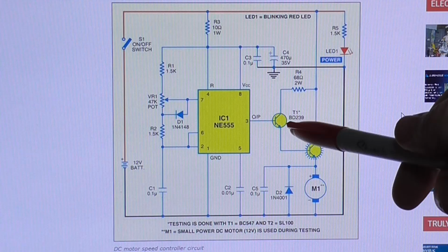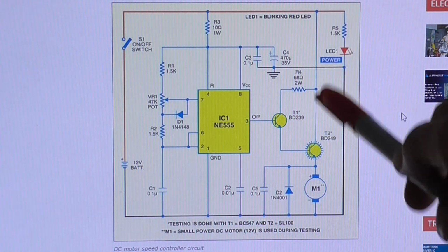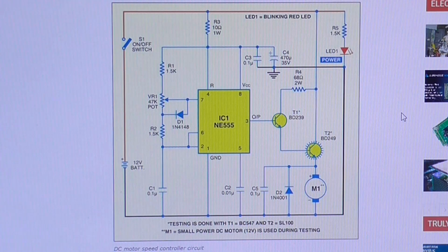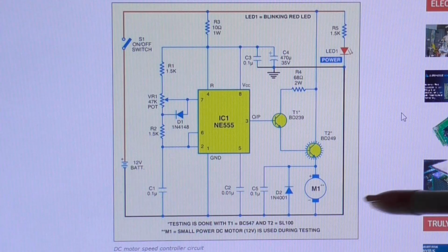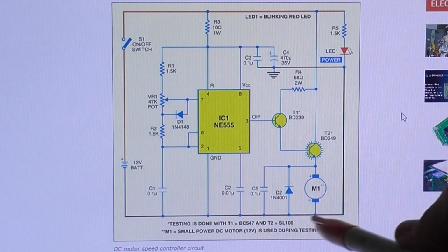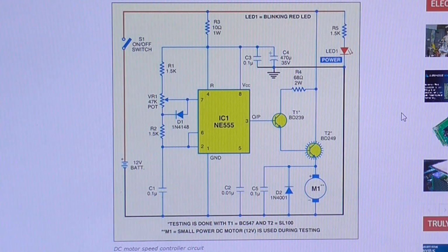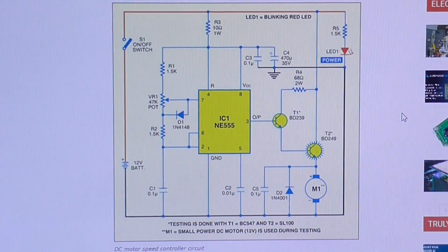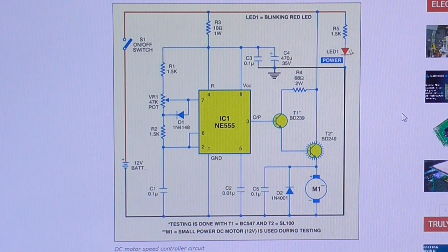However, I think that's overkill there, because it's actually connected in Darlington configuration with this output transistor, which is a BD249, which I also don't have. But because the use of this circuit was for controlling a wiper motor in a car, or van, or any vehicle for that matter, those motors, when they're under load, can draw nearly a couple of amps.